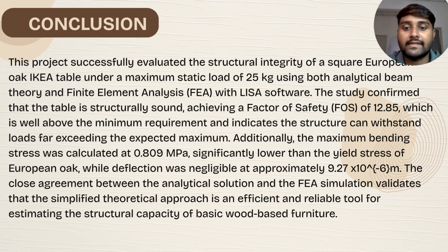The maximum bending stress is 0.809 MPa, which remains significantly below the material yield limit, while deflection is negligible at 9.227 times 10 to the power of negative 6 meter. Furthermore, the close agreement between the analytical solution and FEA simulation validates the reliability of the simplified theoretical approach for evaluating wood-based furniture.